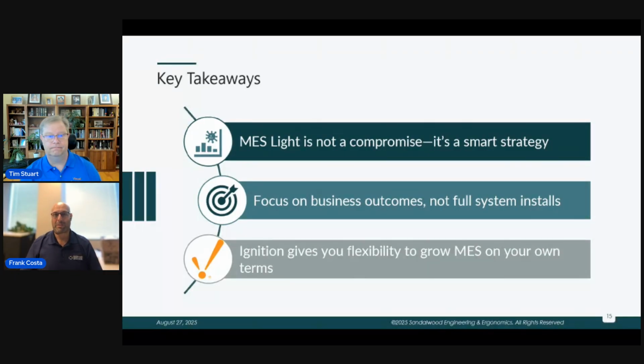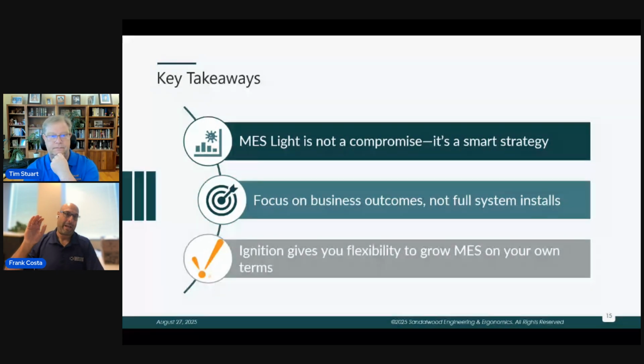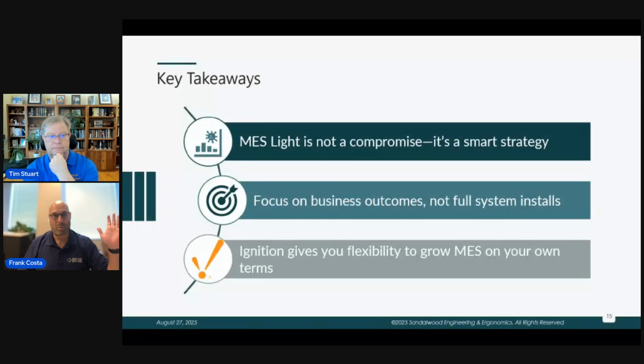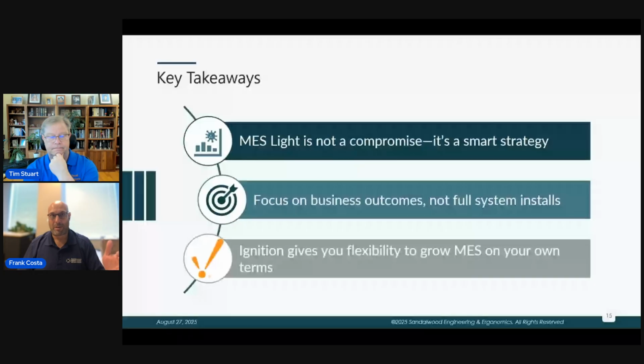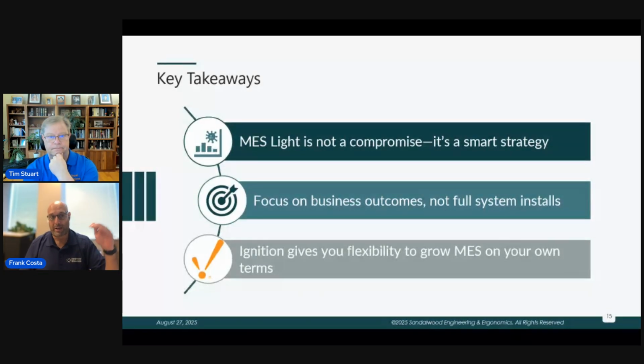And so don't forget that one of the powers of Ignition, we've been talking a lot about the front end, and it can talk with databases and API and REST calls. On the back end, the actual data acquisition, what Ignition was built on 20 some odd years ago, it's about talking to devices. So the drivers, first of all, you can use OPC UA, you need OPC DA. So everything that used to talk with the old protocols is there. The drivers for Mitsubishi, Allen Bradley, Siemens.